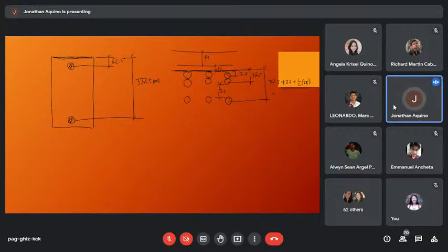Clear distance between layers is 25 plus 1/2 of 25. So this will give a value of 75. Okay, so by Varignon's theorem, A times Y is equal to summations of A, Y. So the total area is the total area of 9 bars.